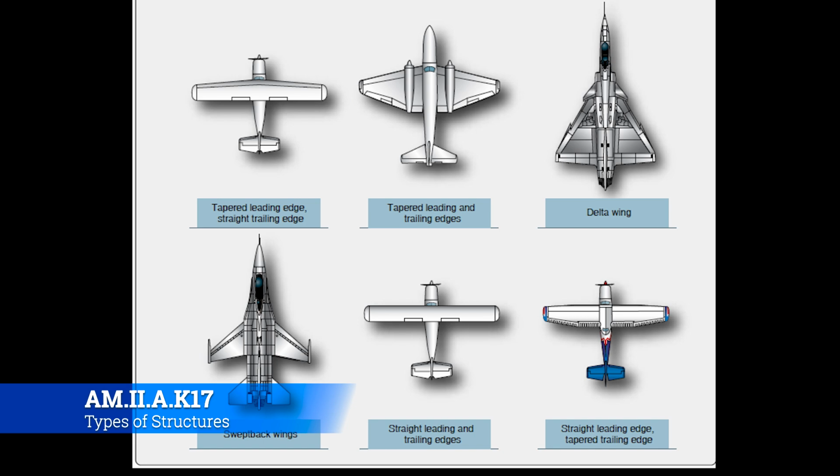All right, so on the right you have the delta wing. So the delta wing is really good for high speed. Now there's disadvantages to it: at lower speeds it doesn't produce as much lift. So you basically always have to be leaning forward on the throttle, and so your Mirages and things like that will use those types of wings.